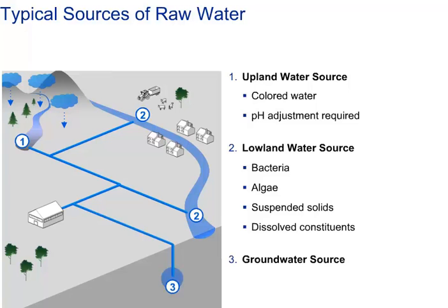Groundwater. The water emerging from some deep groundwater may have fallen as rain many tens, hundreds, thousands of years ago. Soil and rock layers naturally filter the groundwater to a high degree of clarity before the treatment plant. Deep groundwater is generally of very high quality. That's to say, pathogenic bacteria or pathogenic protozoa are typically absent, but the water typically is rich in dissolved solids. There may be a requirement to reduce the iron or manganese content of this water to make it pleasant for drinking, cooking, and laundry use.